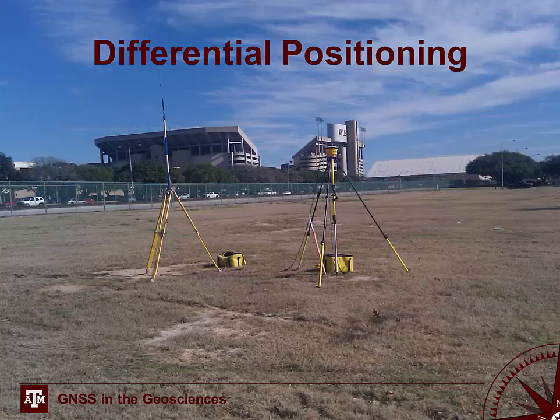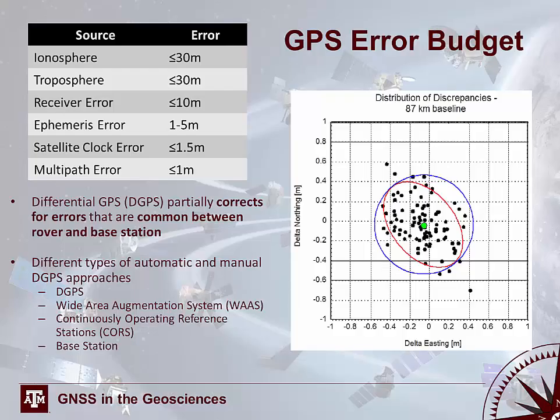The focus of this lecture will be on differential positioning or differential GPS systems, otherwise known as DGPS. So just a brief background on your GPS error budget. There are many different sources of error and each contributes a different magnitude of error. So differential GPS is a way to partially correct for errors that are common between the rover and the base station GPS receivers. So there's several different types of automatic and manual DGPS.